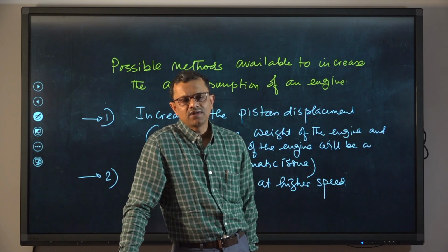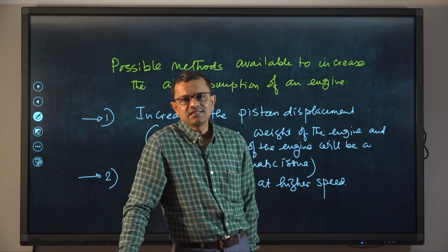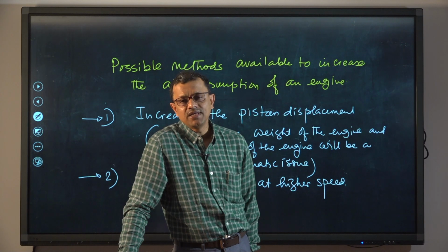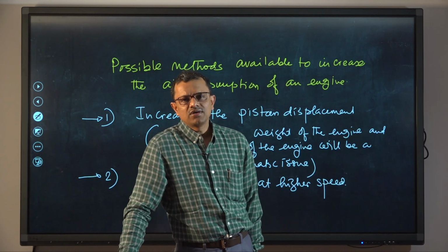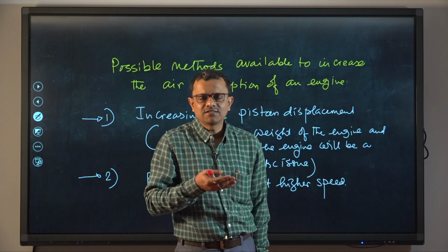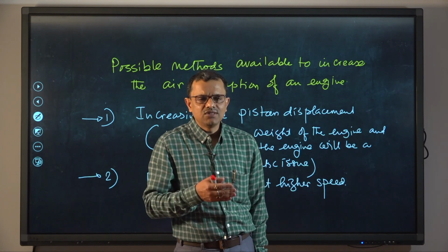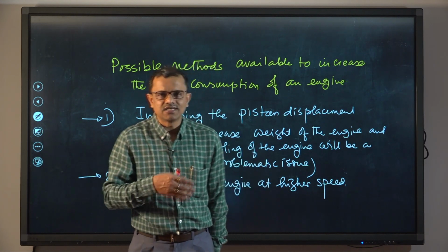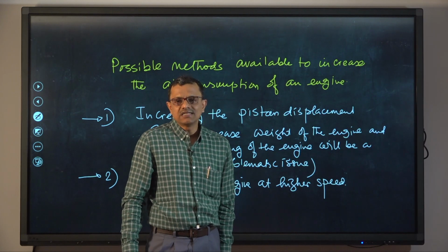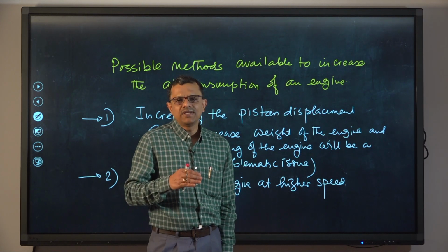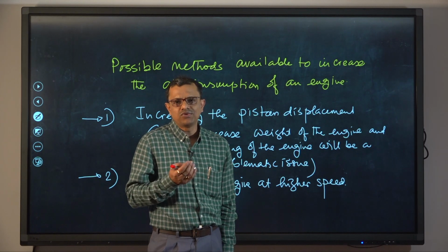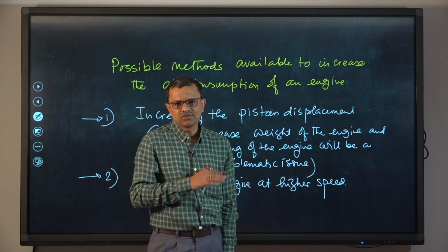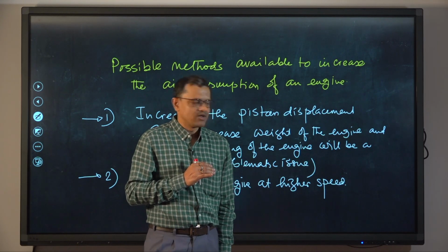Over and above, large inertial stress will be imposed on several parts of the engine, because the piston is moving at a high speed. So the stress due to inertia will be more, and that is known as inertia stress. So larger inertia stress will be imposed on several parts of the body. So this is again not a viable option.